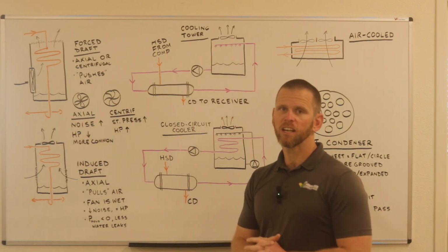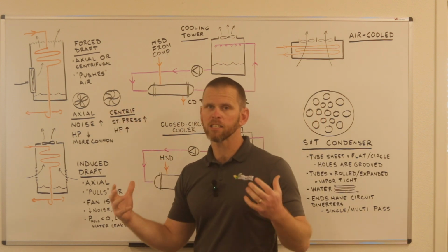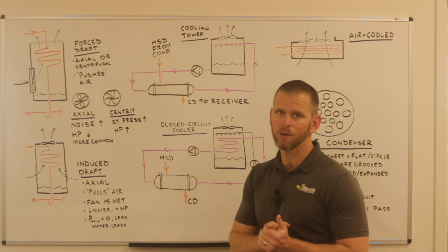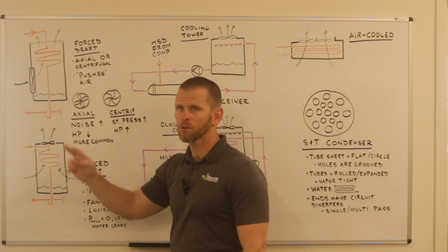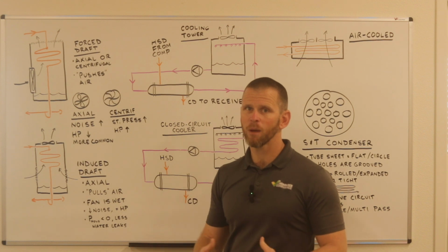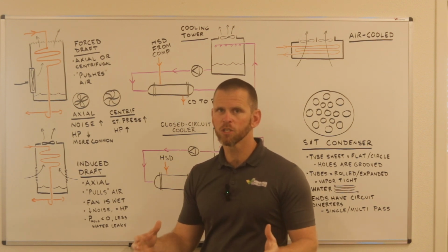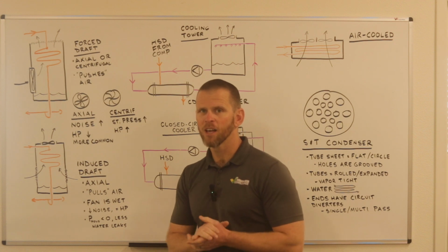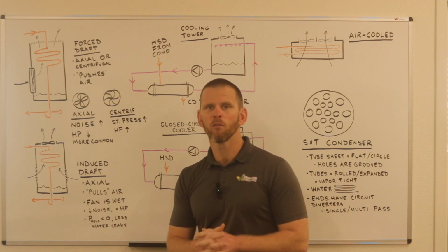But nothing's perfect. Evap condensers do require a lot of maintenance. The sump, the water gets dirty, has to be cleaned. Of course, there's chemical treatment. There's safety concerns. A lot of times to enter the condenser is treated as a confined space. So there's no perfect solution when comparing the three different types of condensers. Pros and cons of each. So that provides that big overview for you.